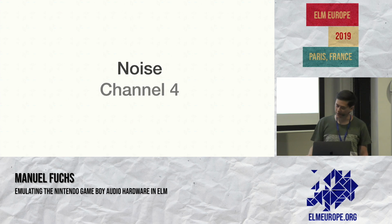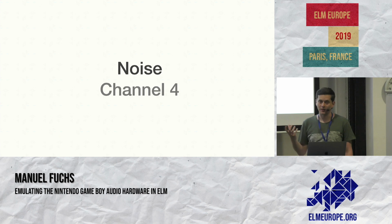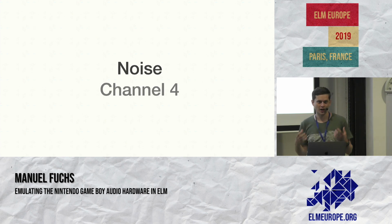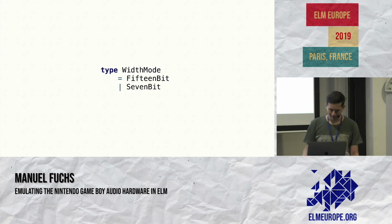Last channel is noise. It's channel 4, and it's quite different to the other 3. It just outputs random white noise. And games can control how coarse the sound is by using one of 2 width modes. This is 15-bit mode, and this is 7-bit mode. And as you can imagine, this is primarily used for percussion and sound effects. As before, I encode the possible width modes in a custom type.